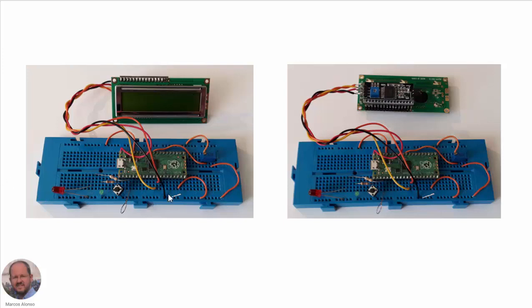So we have other elements, but here we have our LCD display and we have the 4 lines going, 2 of them with the communication SDA and SCL to our microcontroller, and then we have the other 2 connected to ground and to the 5-volt line. Here we can see the aspect on the other side of the LCD.